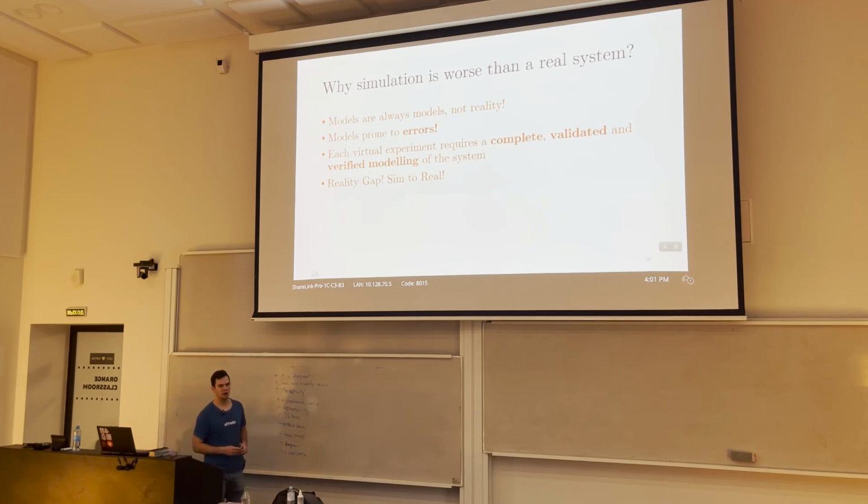And besides that, another problem is modeling of elastic materials. In most simulators, the links are modeled as rigid bodies. But in reality, we do not have such a thing as a rigid body. All details deflect. If it's a plastic detail, it deflects a lot. If it's a metal part, it doesn't deflect a lot, but still it does deflect. And simulators do not consider this effect.